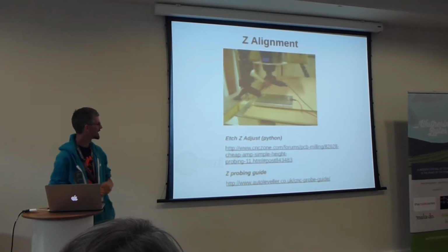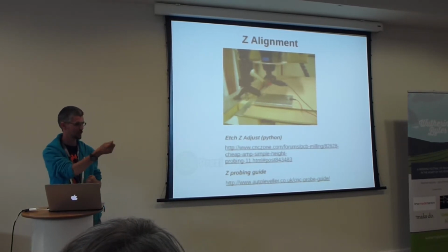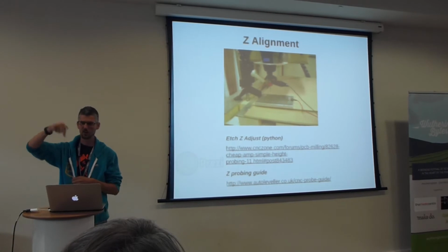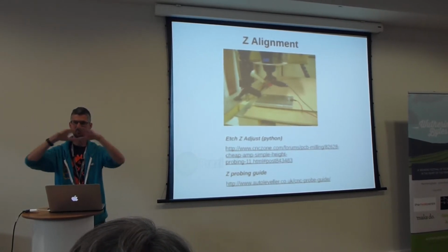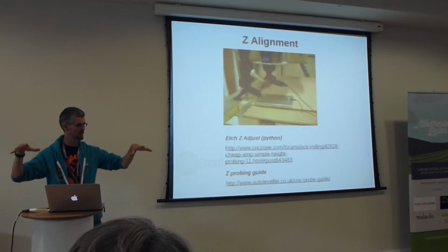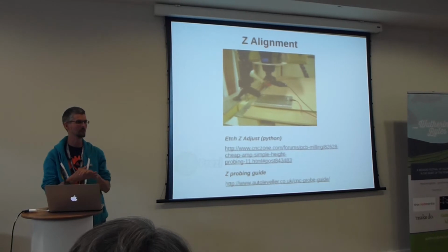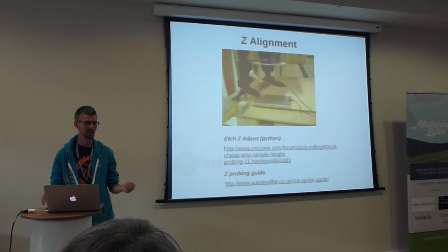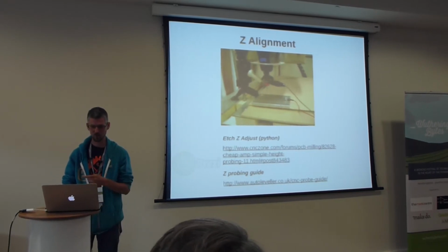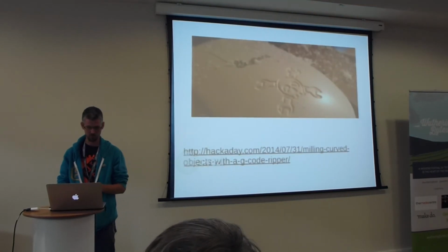So one thing you can do is attach a crocodile clip to your drill, have a little metal plate or straight on your copper board, and then do a kind of XY scanning and probing, generate a depth map of your bent PCB, and then wrap all of your etching parameters around that bent PCB, and then you're etching according to the top. And that is the difference between a usable SMT homemade board and something that is completely hopeless. So if you're doing PCBs, especially with fine pitch stuff, definitely look at that. It's pretty much impossible to do it otherwise.